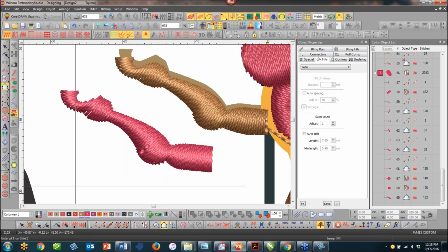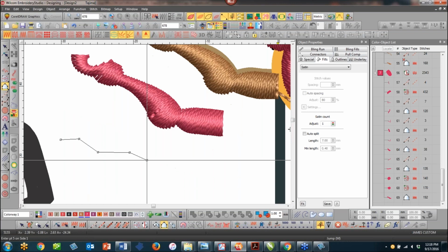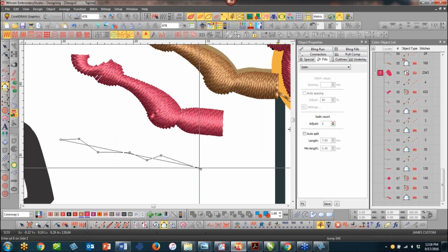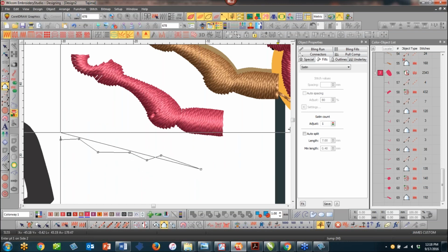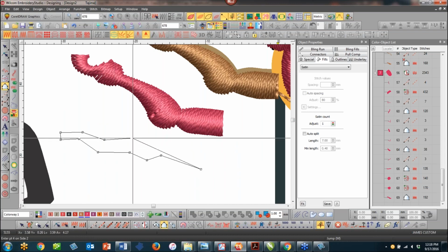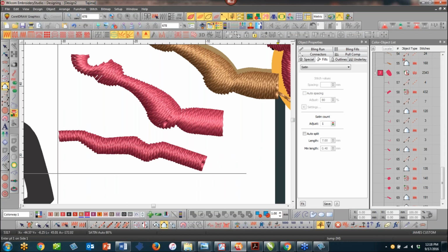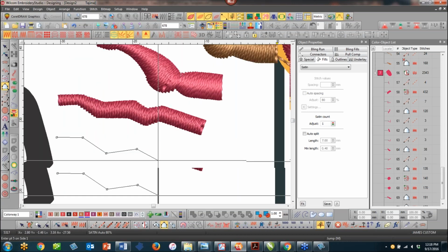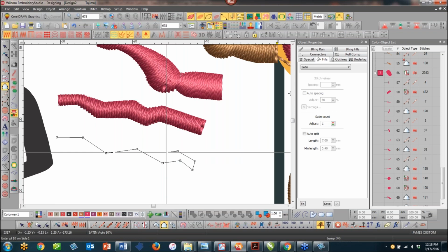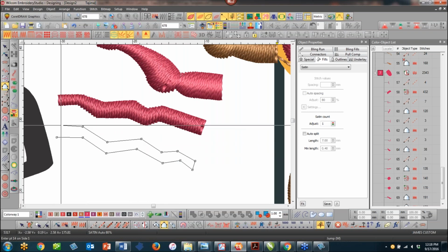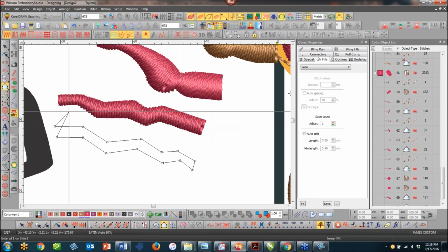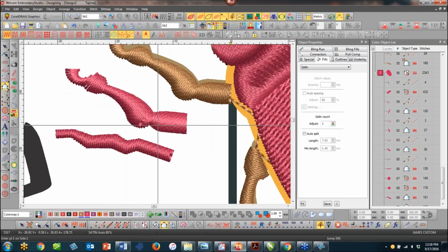So if I choose input B and I digitize something like this, I have to press enter, and I have to do a side B in order for this to take effect, or it won't work, like this one. Now if I try that again, and I try to go all the way around it, this is where the problem lies. When I press enter this time, it wouldn't do anything, because with input B, you have to have a side A and a side B.